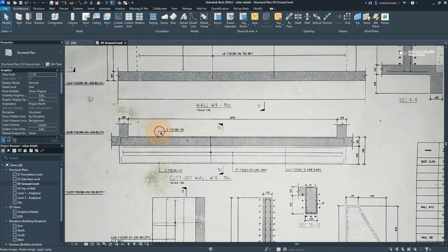So at this first rebar set, we have this top layer provided here, and it has a tag of 3Y12, shape code 38, and bar mark 09. On this other side, we have 3 sidebars as detailed here. We also have our stirrups detailed here. And finally, we have our bottom layer here.